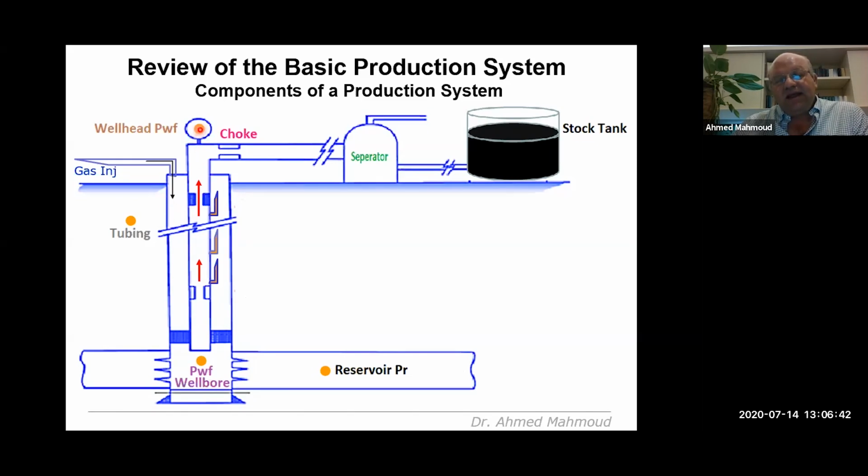Once we are at the wellhead, we have a horizontal migration process, and it will travel to the separator. This is easy because en route to the separator, we have the choke, where we can manipulate the delta P and change the pressures to enable the wellhead pressure to remain higher than the separator pressure. Then the very final stage of the migration process is from the separator to the stock tank, and this is the easiest thing. Obviously, the separator pressure will be higher than the stock tank or storage tank pressure.